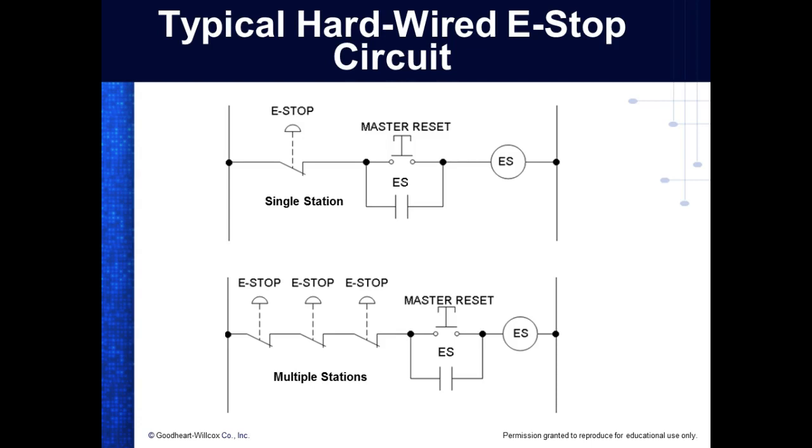Everybody okay? This makes sense. We can put multiple e-stops down a series string. I think I told you about the number 4 Gavilan line at USC. We must have had 25 e-stops in the series string right here. They call it a permissive circuit.